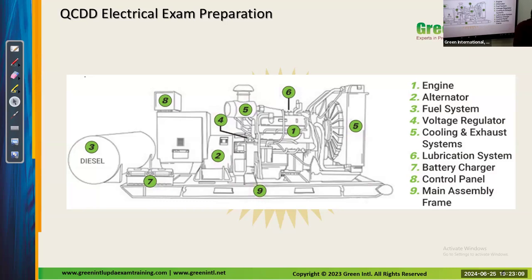Even though it is an automatic transfer switch, inside this system we have mechanical operations. If you have a mechanical operation, what will happen? A spark will be created. Thereby the contact layer may become corrupt, turning black, so it is not able to make contact. That means we need to maintain it.